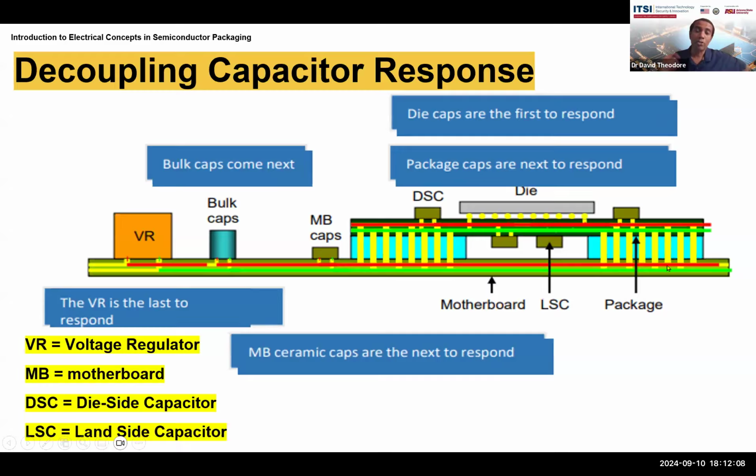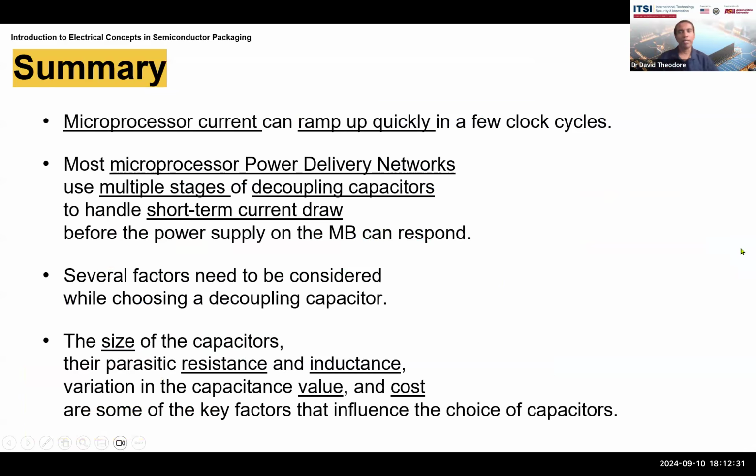And by doing this, a lot of design goes into building in the correct amount of these capacitors at the correct locations on the die to begin with, and then on the package, right? The package as close to the die near the locations that are demanding the current, and then on the motherboard itself. So that gives you an idea of the significance of this.